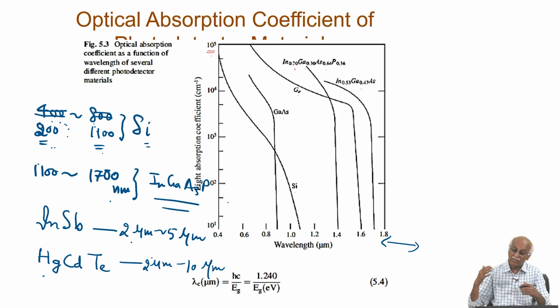Still, there are other approaches to improve the measurement characteristics, such as black silicon, in the sense that the surface of the silicon material is modified so that the number of photons absorbed and electrons produced, that is the quantum efficiency, can improve.